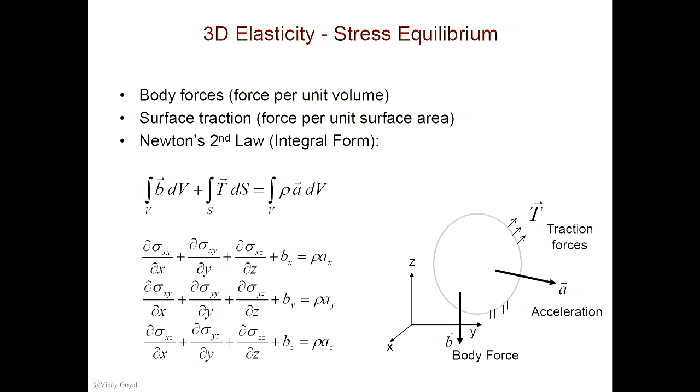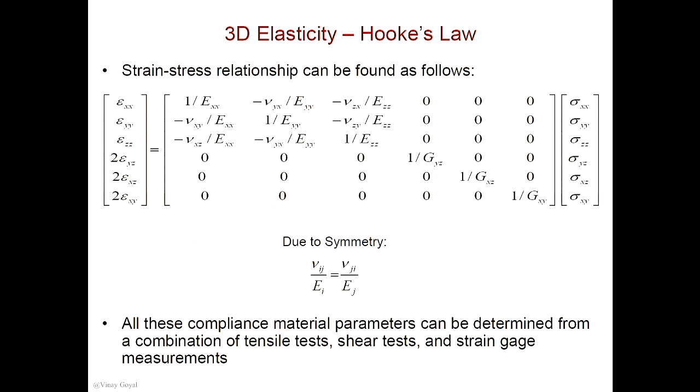We also covered that in a problem, I apply traction forces, body forces, acceleration, and why not keep the acceleration forces? You know how to tackle transient problems now, so we'll just keep that there. And we have 3 equilibrium equations. They're dynamic equilibrium equations. And you can determine from these 3 equations, given the stresses, the strains, the displacements, and the relationships between stress and strain, perhaps the solution to the problem. And you can see it's highly coupled. You cannot really do it by hand quickly.